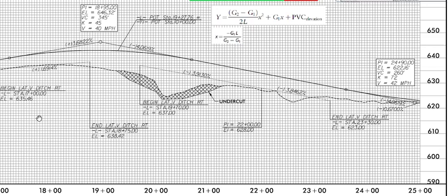And let's start taking a look now at the various components on our design plans. Grades are very important. So our entrance grade is known as G1, and that's going to be positive 3.6822. We're going to have G2, which is our exit grade, is going to be negative 4.0619.